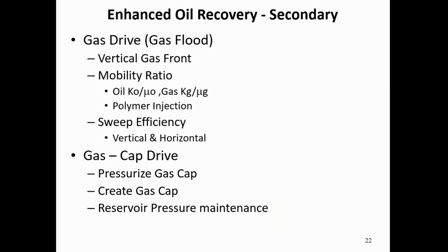But sometimes you can argue with me, what shall I do? If I have a case where my chemical is naughty, and it needs to move far faster, the answer is add some gel materials to your chemicals. Make your chemicals a bit jelly, a bit high viscosity. Make it more viscous. And surface mix it well before you inject it. That could help and make it slow down.